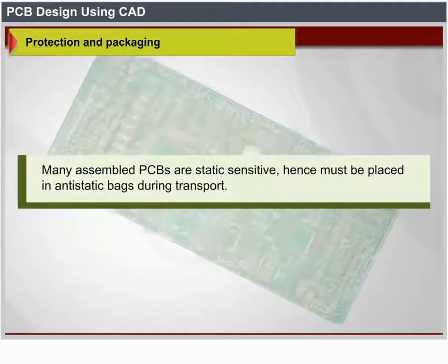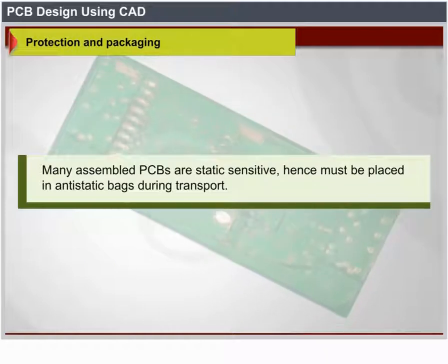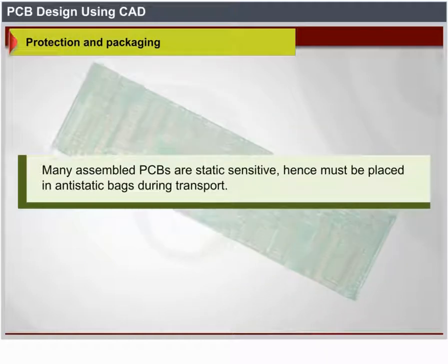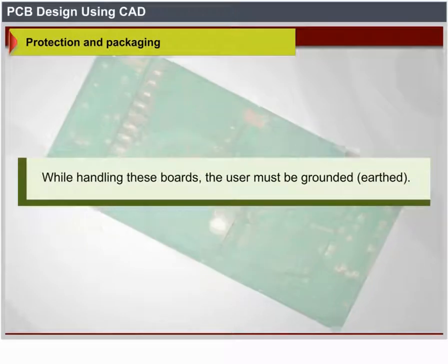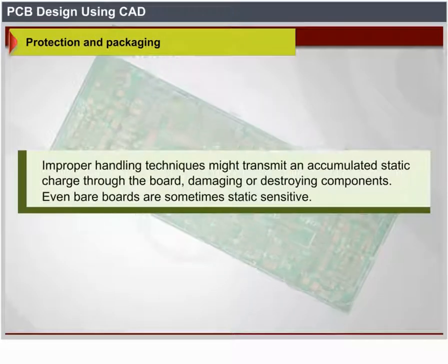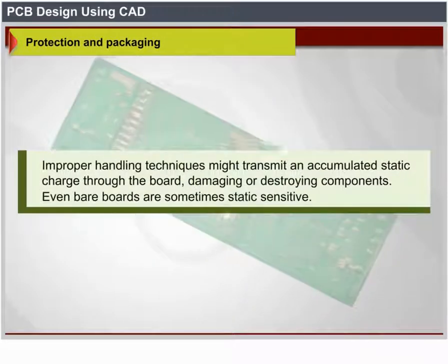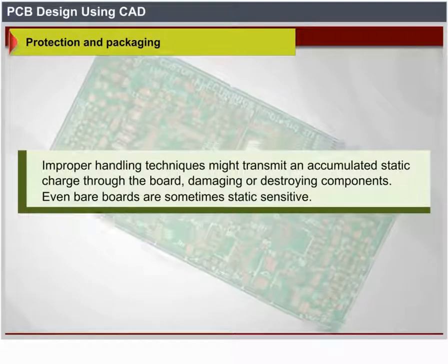Many assembled PCBs are static sensitive and therefore must be placed in anti-static bags during transport. When handling these boards, the user must be grounded to earth. Improper handling techniques might transmit an accumulated static charge through the board, damaging or destroying components.